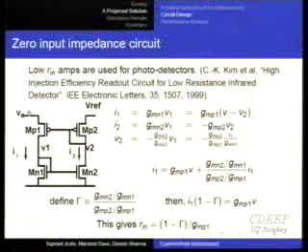So now what have I done? I have opened out the circuit. The resistor has vanished, and this top was earlier going to VDD, but now I connect this to the wire. This is the receiver, so I will connect this to the interconnect, and give a reference voltage here. The ratio of both the top and the bottom is 1. Later we will see how we make it 1. Right now maybe the ratio could be k, but later we will bring it to 1.